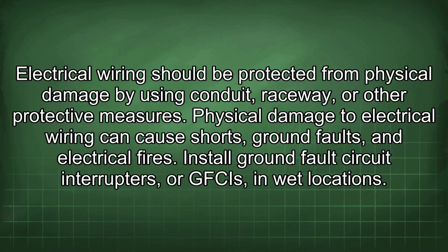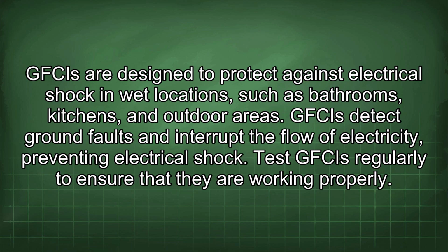Install ground fault circuit interrupters, or GFCIs, in wet locations. GFCIs are designed to protect against electrical shock in wet locations such as bathrooms, kitchens, and outdoor areas. GFCIs detect ground faults and interrupt the flow of electricity, preventing electrical shock. Test GFCIs regularly to ensure that they are working properly.